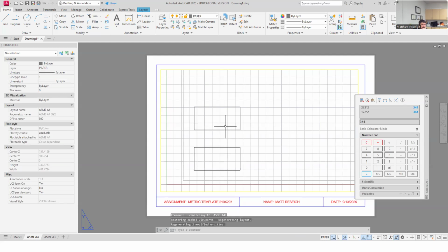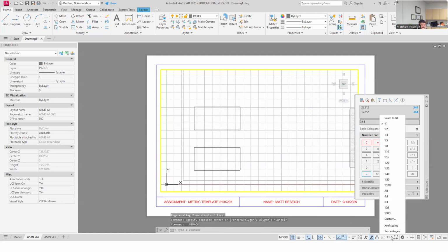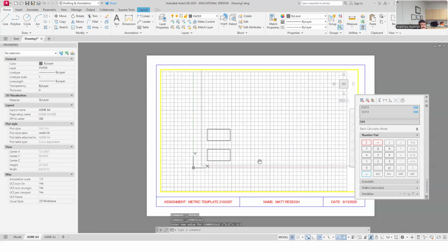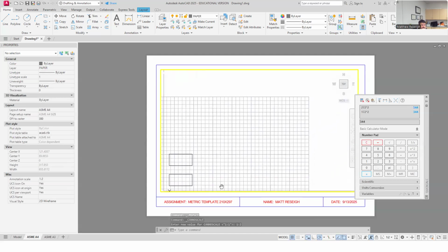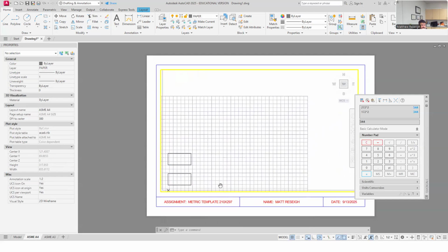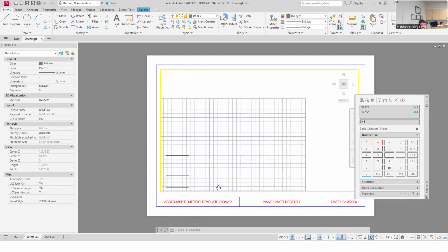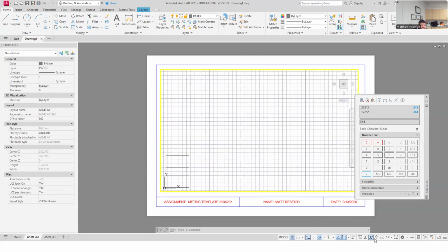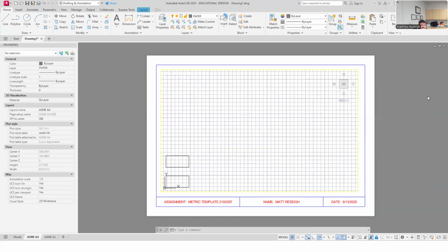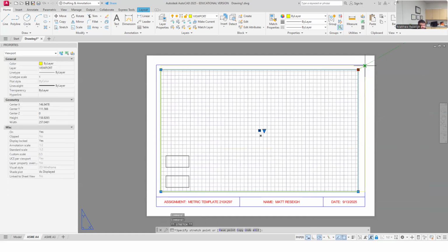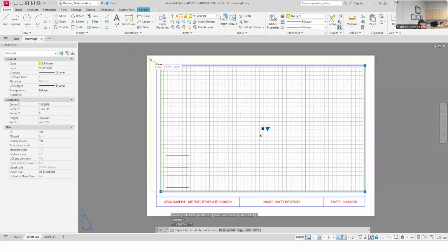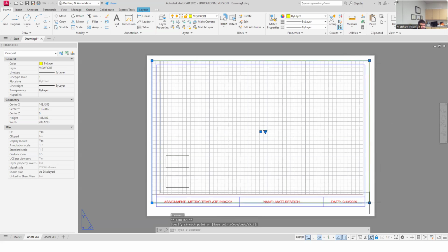You can already see that's quite large. On my paper, if I click into the viewport, it's really going to be, if I unlock this and put it on a 1/2 scale, which is what we want to finish this at. This is how much room I actually have to work with. See, that's why my sheet size kind of fits in my border area here. Let me resize my viewports and make this a little clearer. I'm going to lock this down momentarily. I can get rid of my calculator for a minute. I'm going to jump out here and maybe draw my viewport out to my border area, or even beyond just a little bit, so I can see how that gray box I just drew fits.